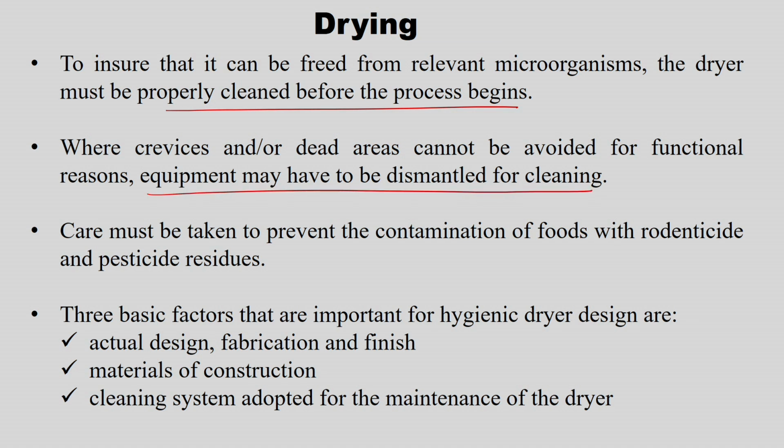So we said while designing and fabricating the dryer itself, we need to take care of these crevices or dead areas. But for functional reasons or functional flexibility of the dryer, if these have to be there in the design, then we need to ensure the equipment can be easily dismantled for extra cleaning, because these areas need extra cleaning. If we are not able to provide that by CIP, at least we need to dismantle the unit for further cleaning by manual.